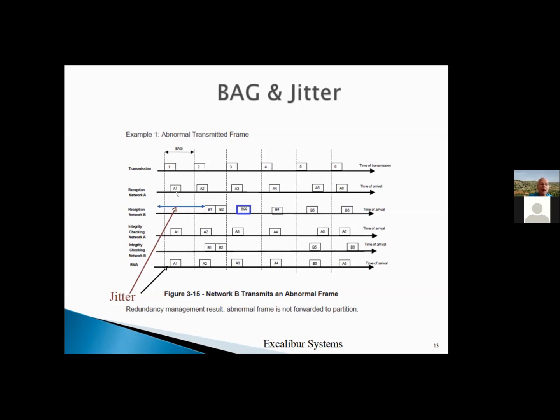Okay, that's okay. And remember, there's dual redundancy. So it was sent out both on A and on B simultaneously. Dual redundancy means different things in different specifications. In some, it means you always send it out on the primary bus, and if you have a problem, you'll send it out on the secondary bus. That's the most common way of doing it. AFDX chose differently. They chose to send everything out on both buses simultaneously and let the receiver throw one of them out. Okay, so based on what?